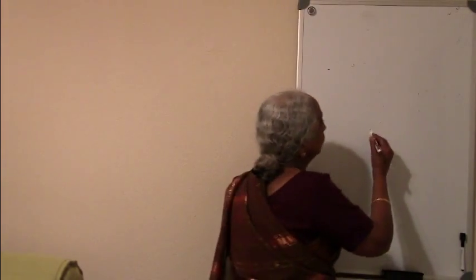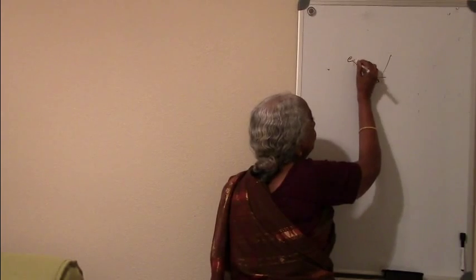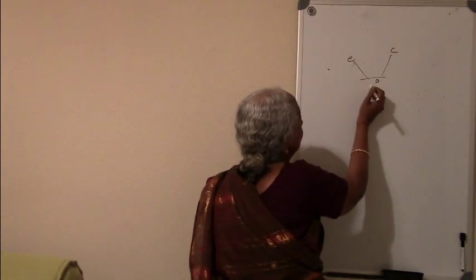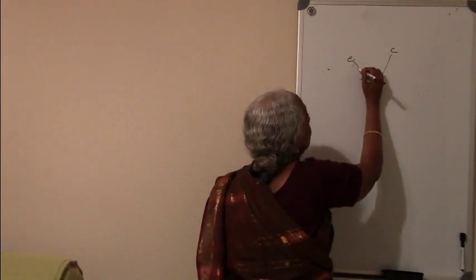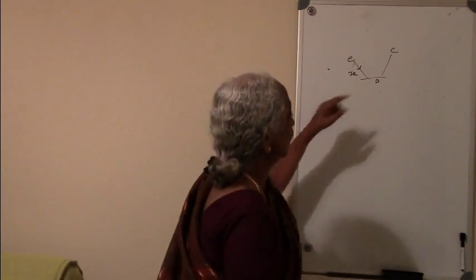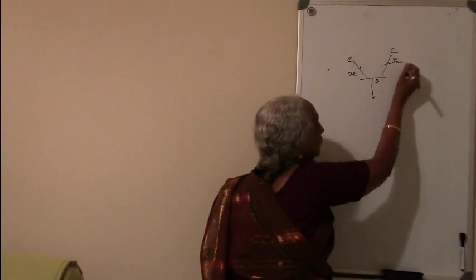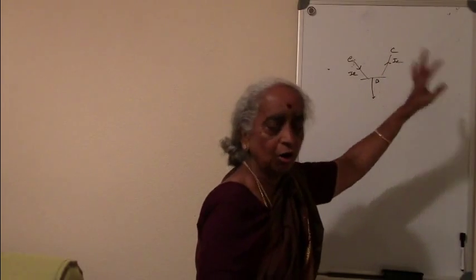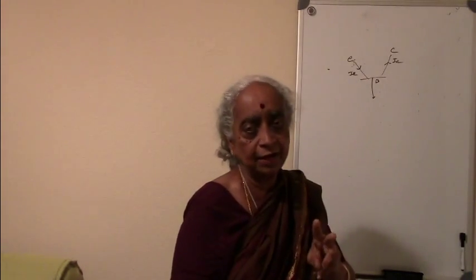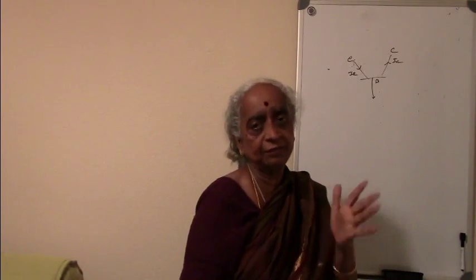Now in the case of common base that you see, base is going to be the common one. Here you have the emitter and here you have the collector. So the base is going to provide this. So your IE will be my input. Of the IE that is coming along, a negligible fraction of the order of microamperes may go like this, much will go as IC. In this case, IC is the output. Always IC will be the output. Whether it is providing the input from the base or from the emitter, that should be distinctly known in the different modes, according to which your input current will be known.